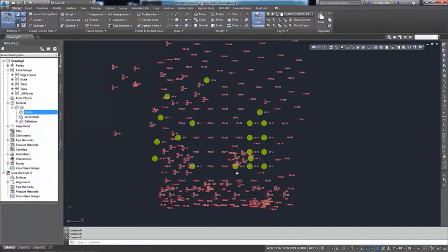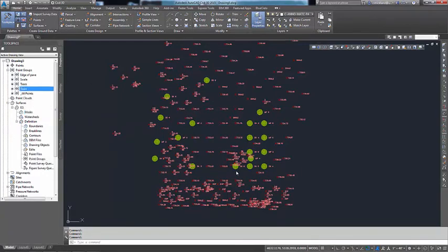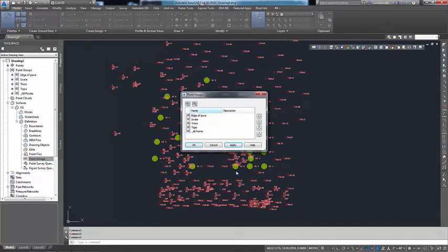For all of my class, I'm not going to mess with masks or watersheds right now. All I really care is how this thing's being defined. And to define a nice quick surface, in this case here, I've got topo points already put into a point group. So since I don't have any of the other categories except for point groups, that's my only choice. We'll right click on that, go to add. Now in add, it shows me all my point groups. I'm going to click on topo, say OK.